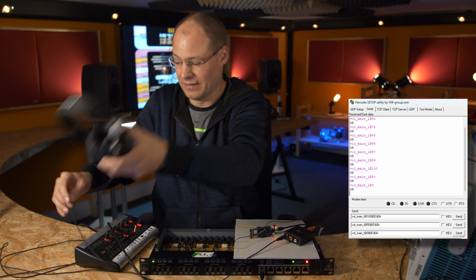At 50, only disturbances. So what is going wrong here? Now, in the calculation, we have to pay attention to the fact that we are dealing with pulse-coded modulation, or PCM audio, with signed integer samples, and thus the most significant bit is the sign bit. Up to now, we have ignored this in the multiplication. We are just multiplying bit vectors. But by adjusting the volume block, this is quickly corrected.